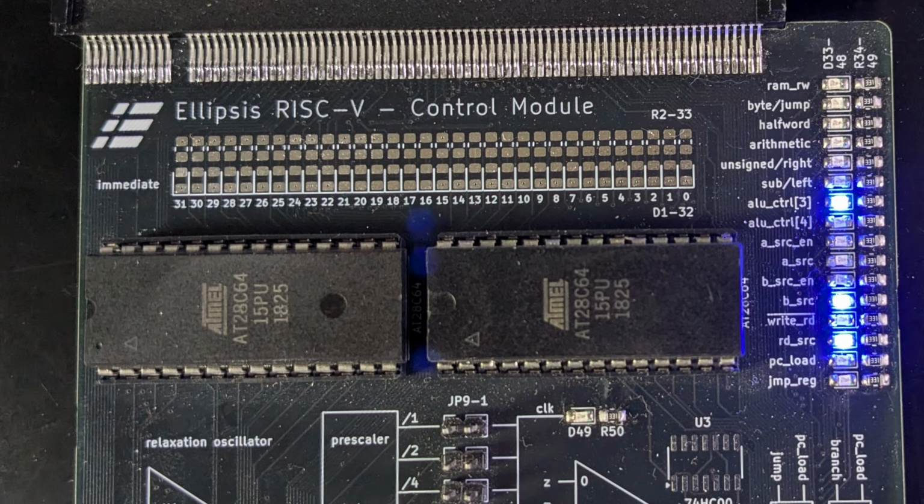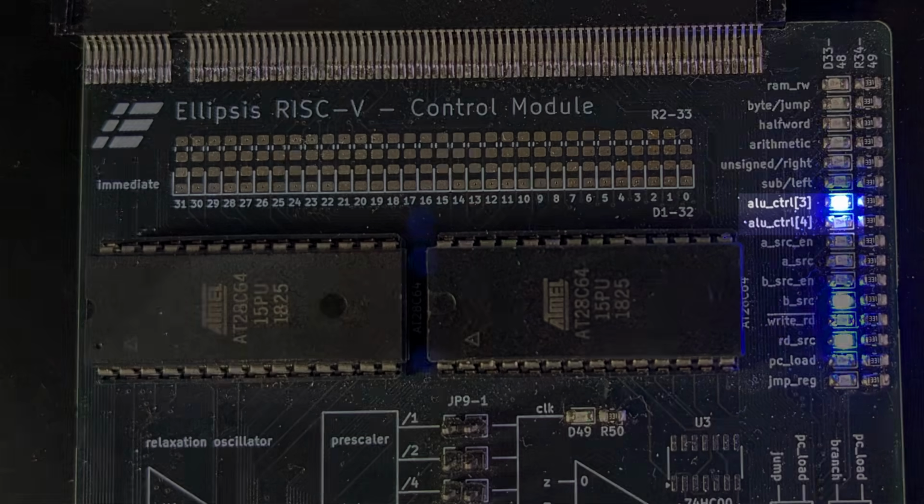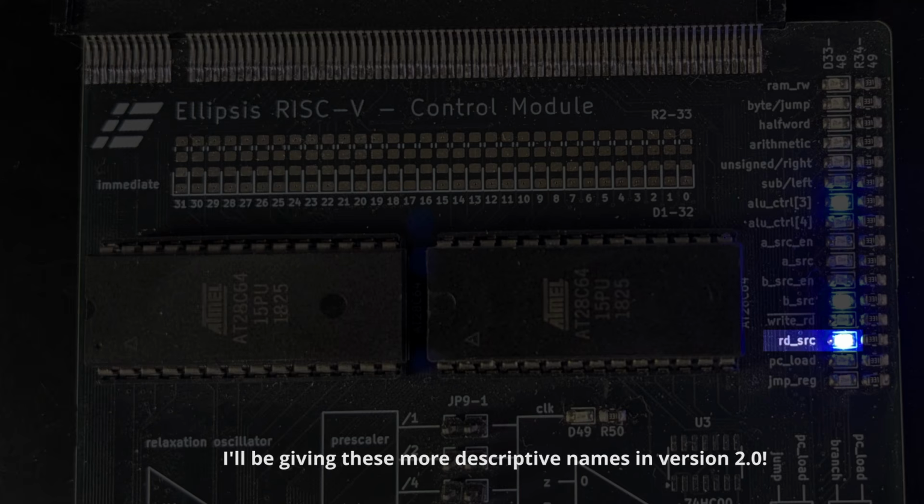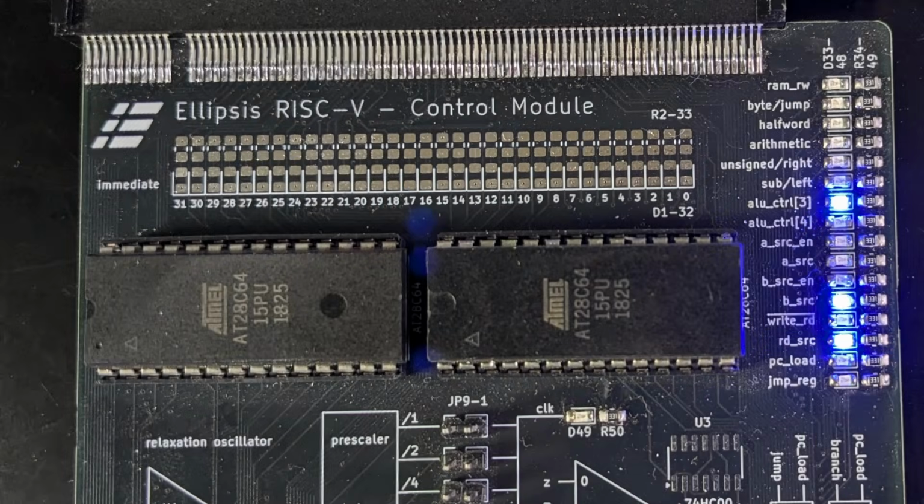The next instruction is a load word instruction, so reading from memory. Again, we're selecting the add sub module, and this is because we need to calculate the memory address. And we do that by adding a register value to an immediate value. And so the B source control bit, that is indicating that we want to read the immediate value into source B of the ALU. And the RD source control, that indicates that we want to write the value that we read from memory into the destination register. So these are all as expected, and I'm going to call this working.